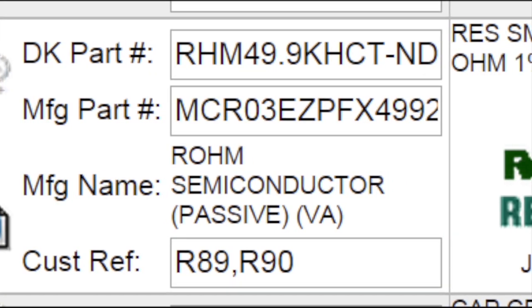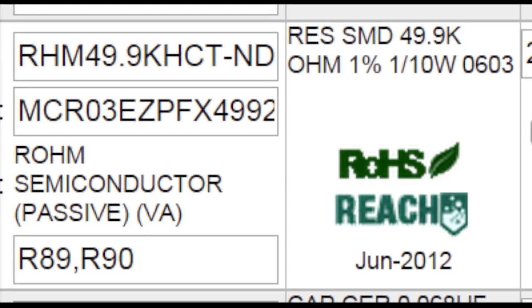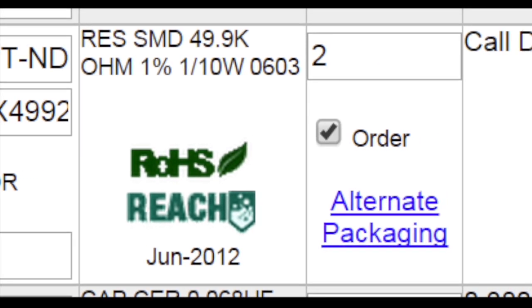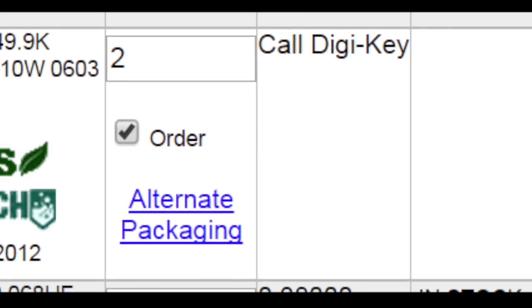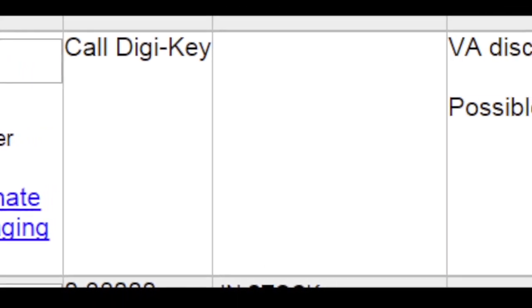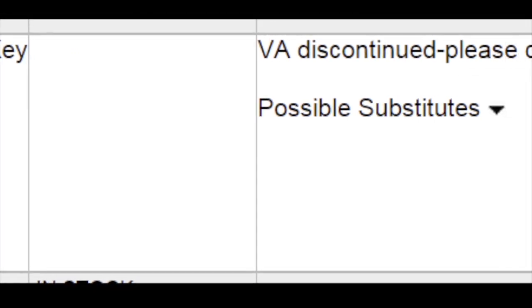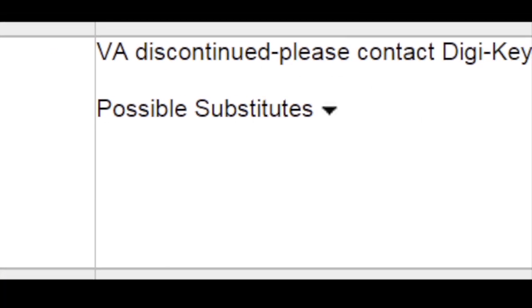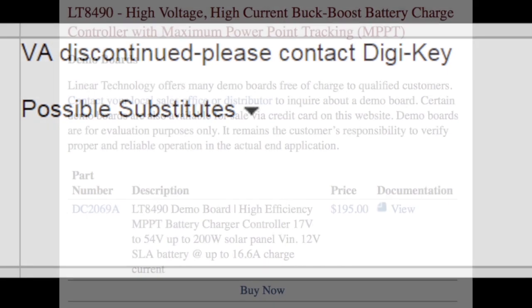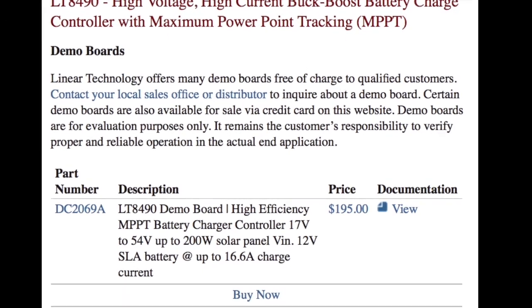Component validation. It's not uncommon to find that the parts in the reference design are either out of stock or out of production. One of the key steps in reference design reuse is updating the component bill of materials to reflect currently available components. Reference design comprehension.